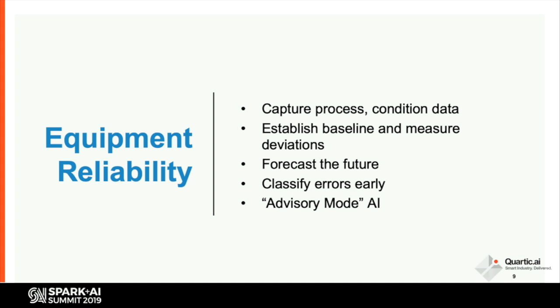Now, unless we merge condition and process data, we can't really create the exact context about an equipment's health. The idea is that if your microwave is vibrating more in order to keep the same temperature, that could be a sign of degradation of the microwave. That could lead to eventual breakdown, or it could lead to higher energy consumption. So the key insight here is making sure that we have the condition data being monitored and combined with the process data to create the right kind of context.